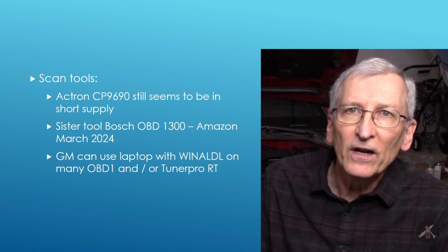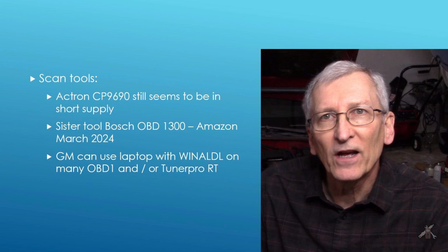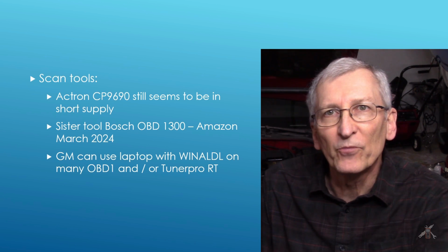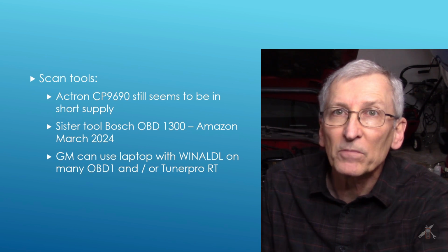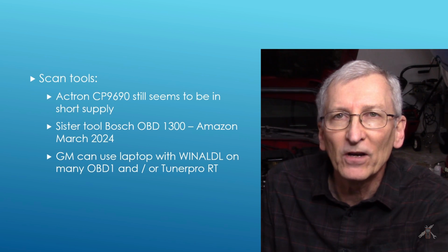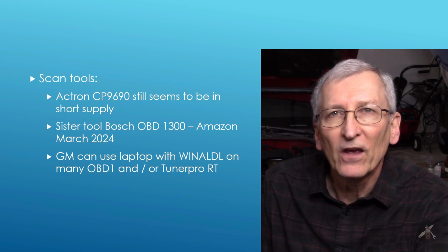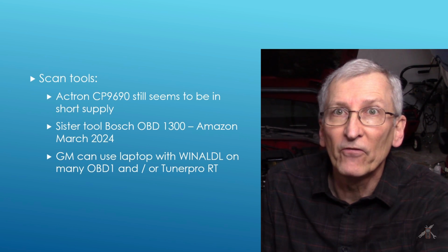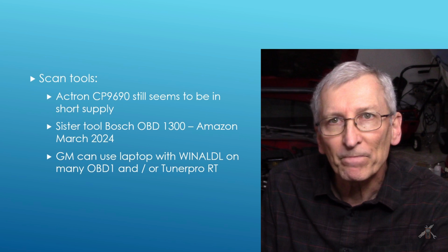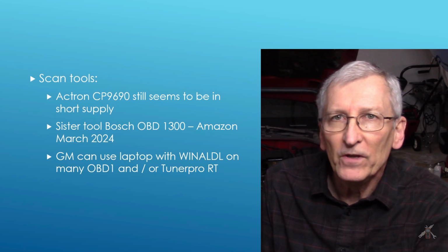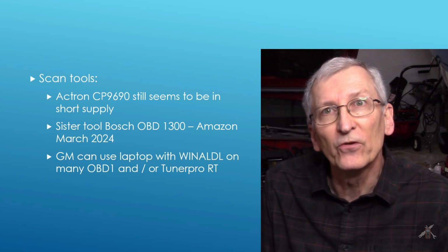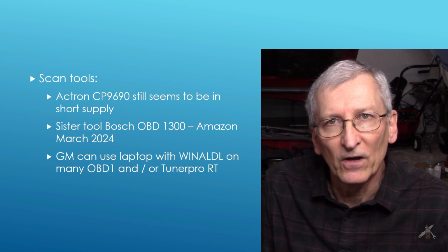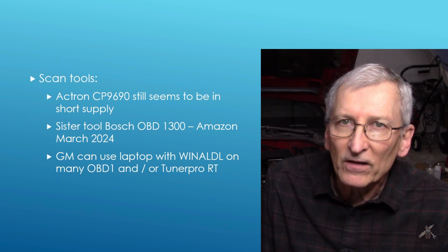Or you can get out your laptop computer and you can get a copy of WinALDL, get the USB cable, go back on my channel and look, and you'll see how to set up WinALDL or TunerPro RT. You need the RT version to get real-time data. But either one of those tools can log data for you if you get the right USB cable. They take a little bit more setup.